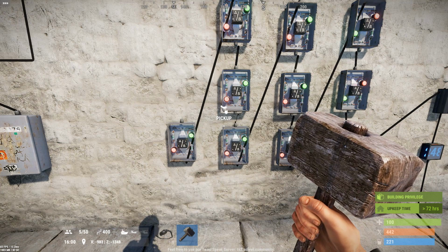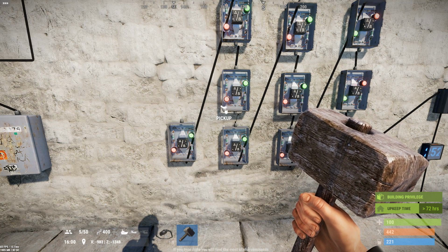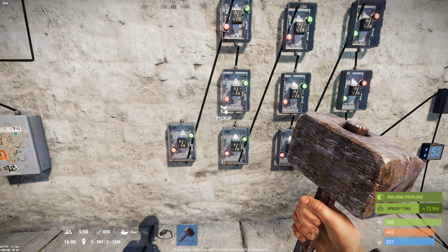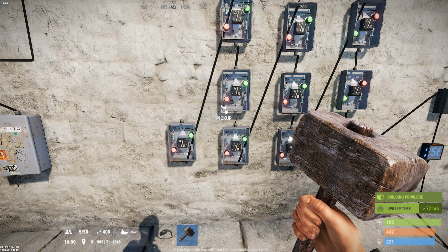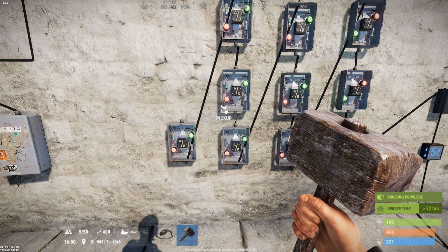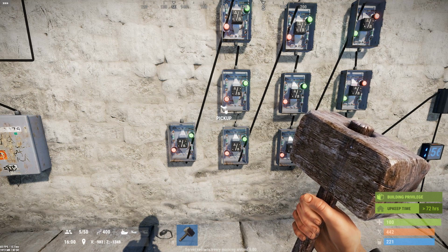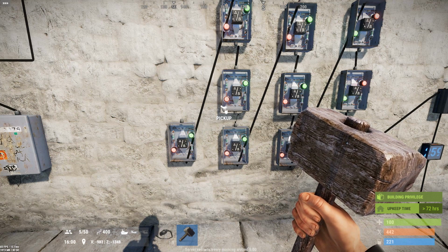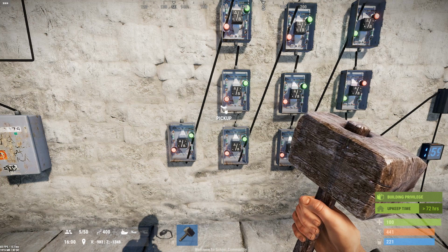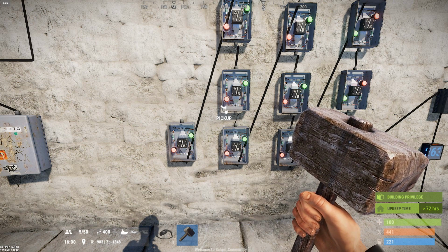It wouldn't matter, by the way, which one of these I hook up, because the OR switches and the AND switches and the XOR switches all pick the better source of power when their condition is met. So an OR switch, if you had 2 power sources to it, is going to pick the higher of the 2 inputs. The AND switch, you have to have both power inputs applied, but it's going to output the value of the higher one. And the XOR switch has to have one that's off, and of course it's going to take the one that's on.